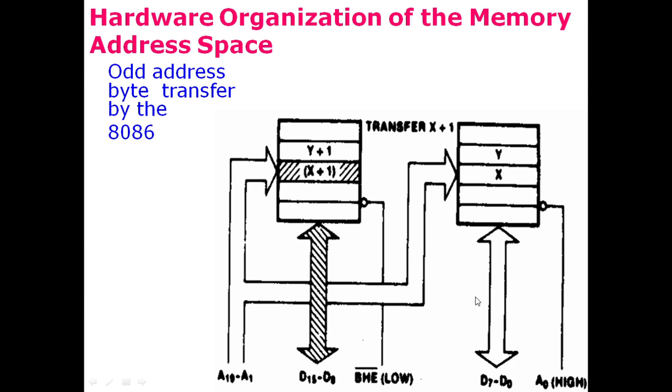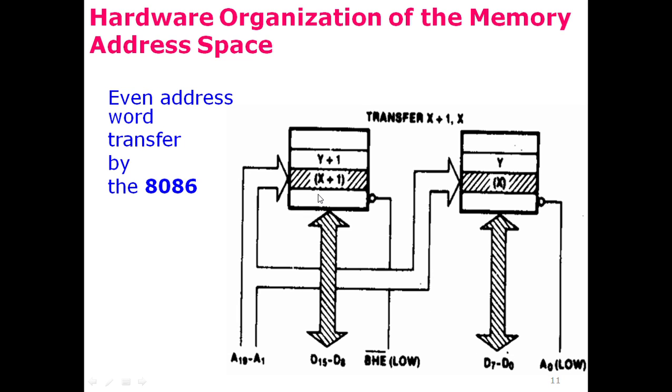So we see that 8-bit data from the low bank can be read, and 8-bit data from the high bank can be read, as well as 16-bit data, which makes one byte from the low bank and one byte from the high bank read at the same time.